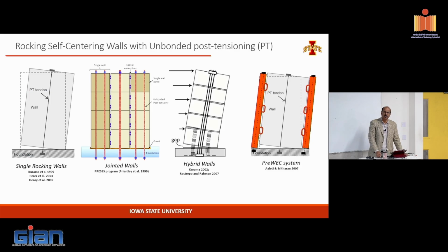So what are these hybrid walls? They call them hybrid walls because they have unbonded post-tensioning and then rebar. In the hybrid moment frame, this concept was introduced, so they took that here and called it a hybrid wall. There's nothing magic about it. But we argued that that concept could provide resistance, but you cannot replace the rebar. These are supposed to be what we call a more resilient system, providing functional solutions, so after the earthquakes you can use them. But if you had to replace rebars, there's no way it's going to be cheap or possible to do.